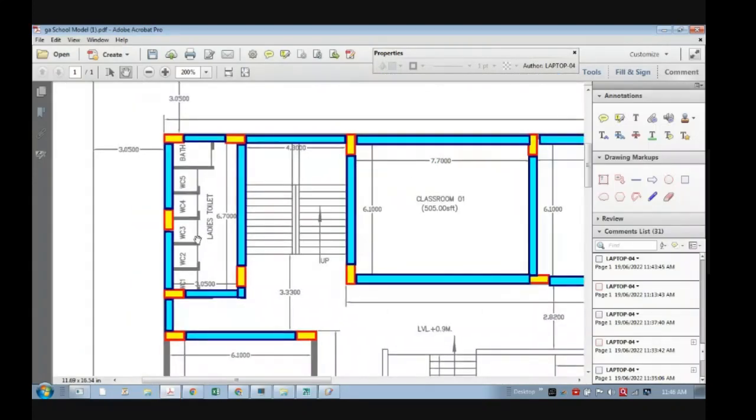Now tell me, let's say these are lightweight partitions. You can ask the architect whether it is a brick wall, a glass wall, or what. So there are partition walls which are very lightweight. So I can ignore these walls as far as my beams are concerned. I will not provide a beam below each smaller wall, because these are very thin, lightweight partition walls. It may be a glass wall, a wooden partition along with tiling, or a 4-inch Siporex wall.